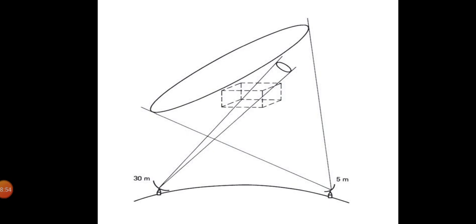By placing the satellite in an inclined orbit, the north-south station keeping maneuvers may be dispensed with. The savings in weight achieved by not having to carry fuel for these maneuvers allow the communication payload to be increased. The satellite is placed in an inclined orbit of about 2.5 to 3 degree in the opposite sense to that produced by drift. Over a period of about half the predicted lifetime of the mission, the orbit will change to equatorial and then continue to increase in inclination. However, this arrangement requires the use of tracking antennas at certain ground stations.